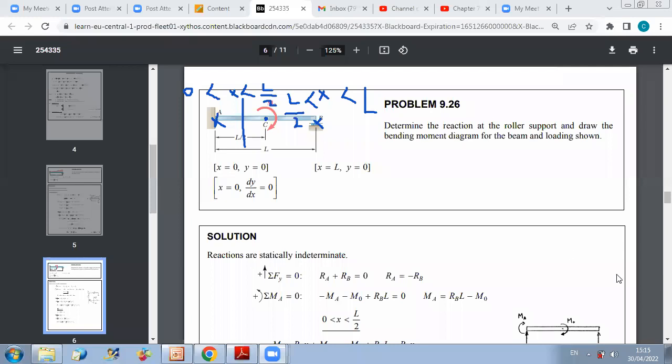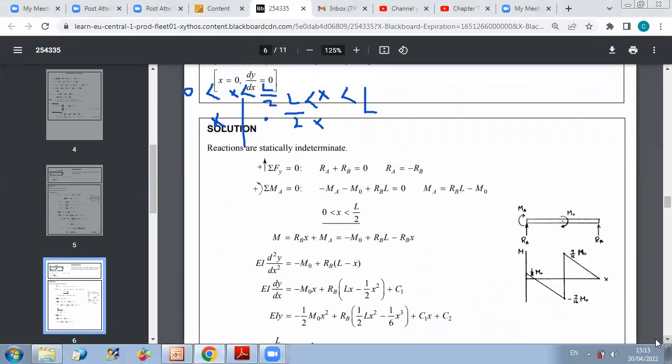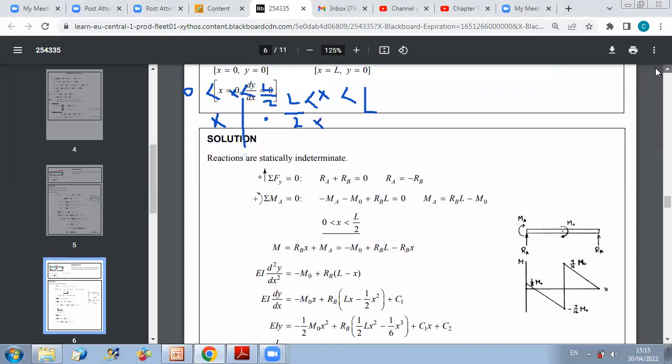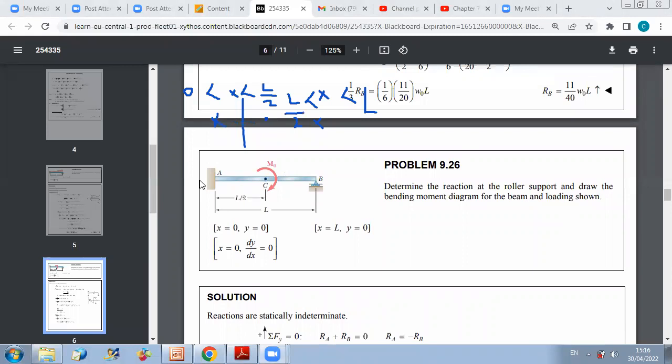So now to start with, if we consider the expression of our first section, here we have, for the first section, we can keep this part, because we don't want to get the unknowns AX, AY, MA involved. We just want to find C1 and C2 of the equation, but we can select this part because it will only include BY and it will not include AX, AY, and MA. And why we need to do the 2 sections here?